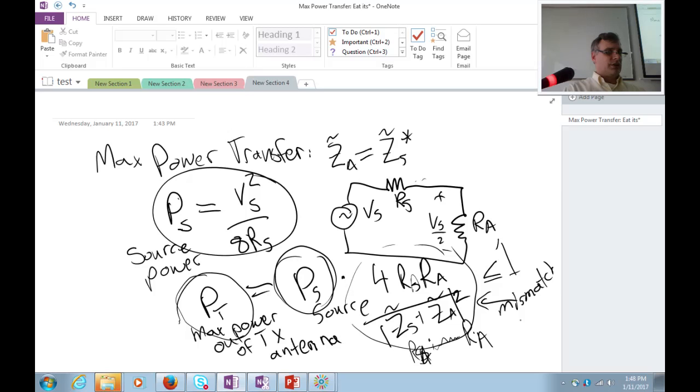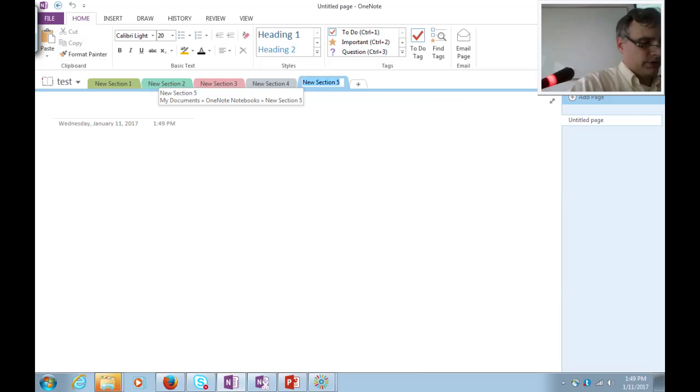And so that's a different ball of wax. And in RF engineering, we tend to account for that in a different term in our link budget analysis. Usually what we call a gain pattern in antenna and RF engineering, that's where you lump radiation losses, radiation inefficiencies. Here we're just talking about antennas and circuits, and so this is really a mismatch loss. We're not efficiently coupling power into the antenna. So that's at the transmitter.